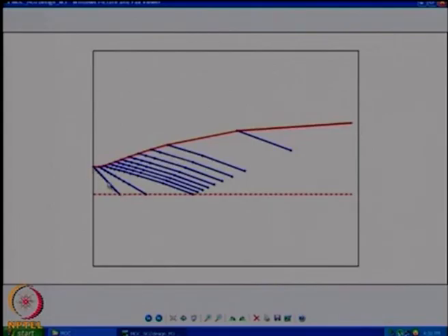Once I have done this, the remaining characteristics are whatever we did before. From the second point here, go to the wall, the circle goes and ends somewhere here for me. Actually the circle ends here for me. So the first point goes there inside the expanding circle. From there I send out a characteristic that will again have 10 points. The third point from here goes there, forms the second point of this characteristic, and then becomes that last point on my expanding circle till there.